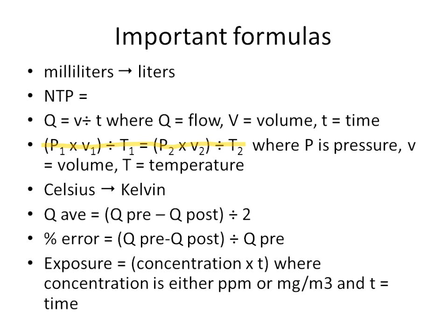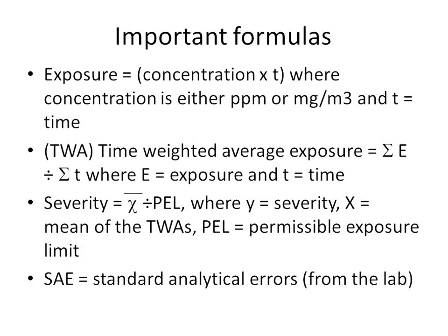So exposure is the concentration times the time, and that is when we're going to time weight the exposure. So remember, the concentration is the value, either the parts per million, or another way to see it is milligrams per meter cubed. So what's the weight of the material that I have on the surface area of my filter? And that material was gathered over a certain set of time. So concentration back from the lab times the time it took you to run your pump and gather that concentration.